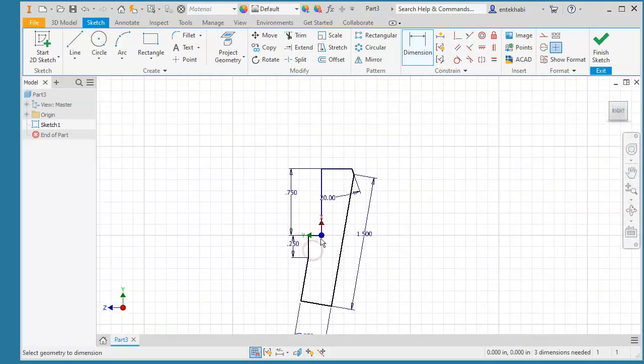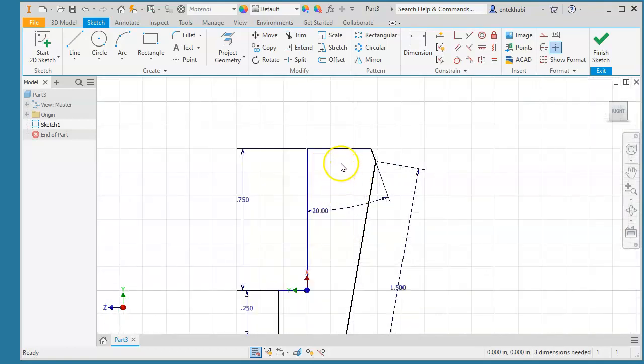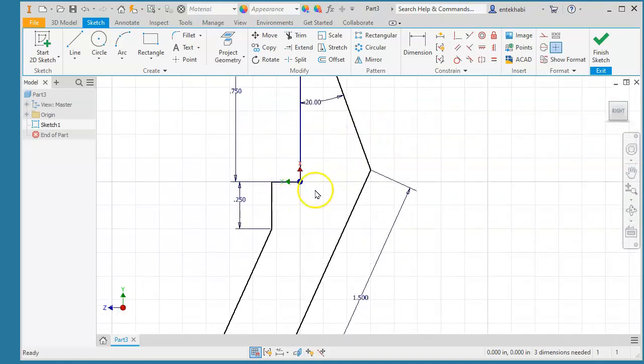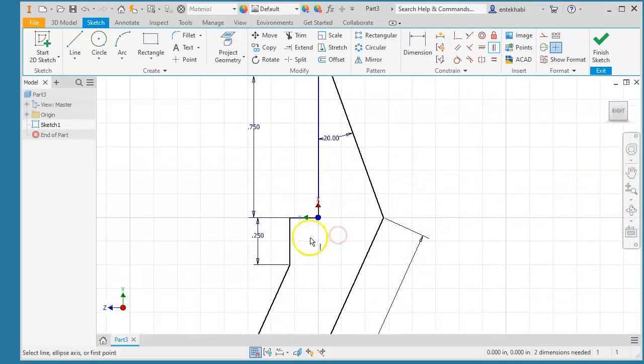And now one of these points here is the critical one that you need to make sure to constrain, otherwise it would behave like this. So this one has to come down and be aligned with the origin, actually. That's the one. And in this icon, if you notice, Y is parallel to the horizontal direction. So make sure you select the vertical relation,